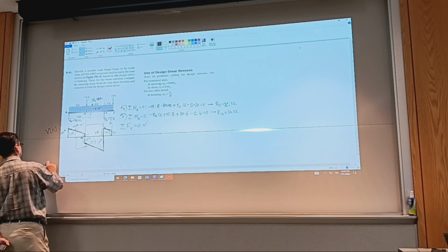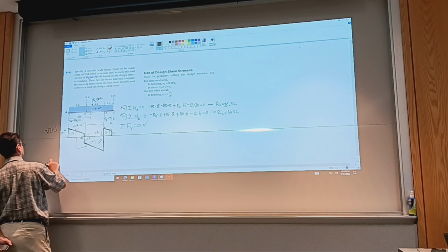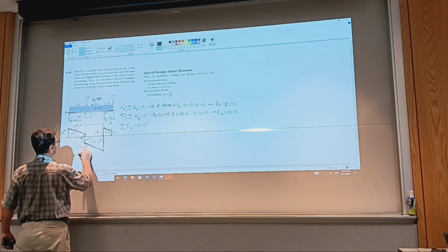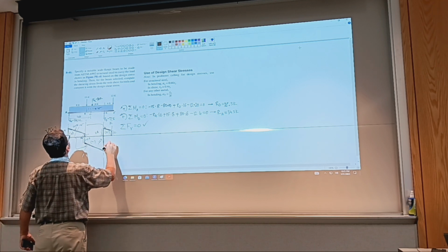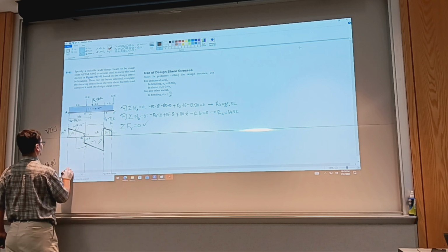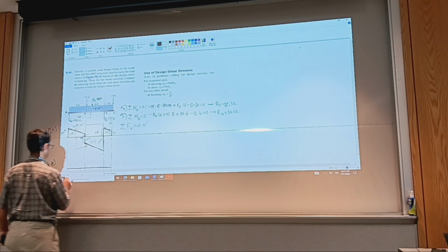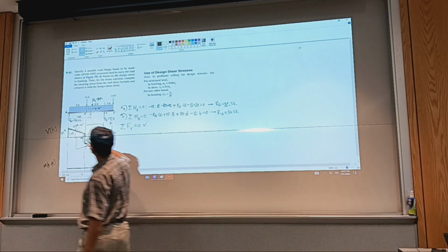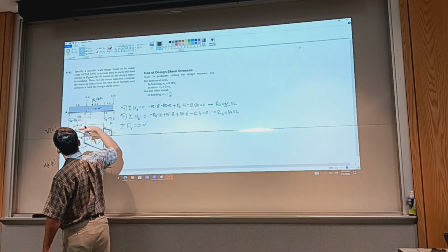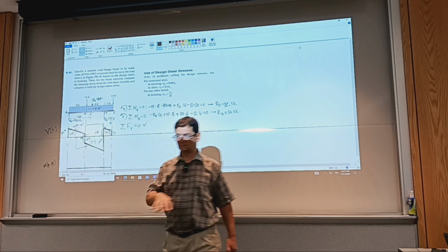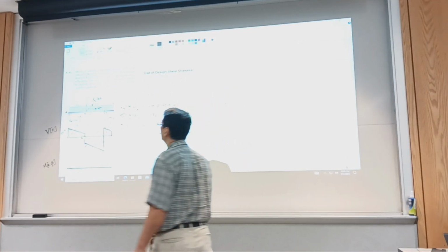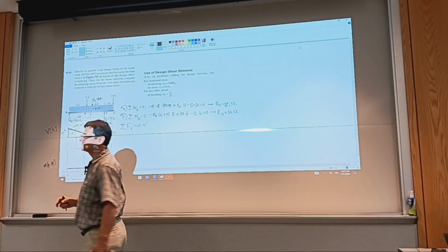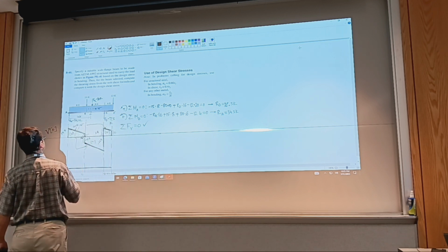So I have M in units of kilo-pound-foot. I draw the x-axis. Again, we'll have some alignment of points at A, B, D, and E. Draw the x-axis first. And because I have these lines not constant V but rather sloped, the moment diagram will be parabolic. It begins at 0 and should end at 0. I don't have concentrated moments or reaction moments at the ends.